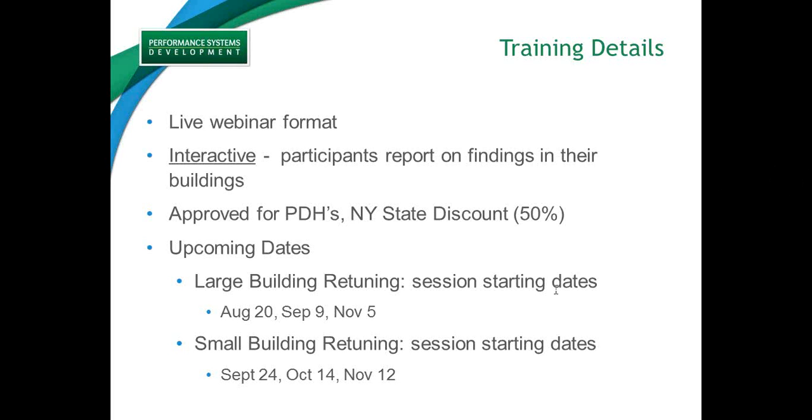So now going back to people's questions, I'm going to try to go in order of what we had here. Patterns. So really the question was, how do you integrate, would an infrared or thermal scan of the shell be part of retuning process, and why not integrate ASHRAE protocol into the whole process? Definitely. I mean, if you can bundle this process as part of a larger value proposition to the property owner, go for it. Definitely a great thing to do. Like I said, there is a component of this large building retuning is to walk through the building.